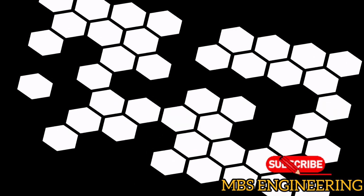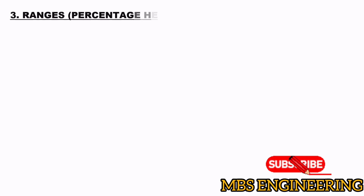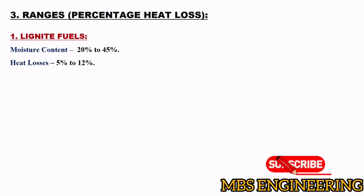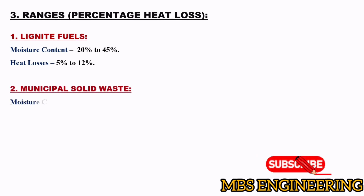Next, we will learn and understand the ranges of the percentage heat loss due to evaporation of moisture present in fuel in the boiler system. Let's look at how different fuels behave when it comes to moisture content and heat loss. Next, in lignite fuels, its percentage of the moisture content ranges from 20% to 45%. Its percentage of the heat losses ranges from 5% to 12%. Next, in municipal solid waste, its percentage of the moisture content ranges from 25% to 50%. Its percentage of the heat losses ranges from 8% to 15%.